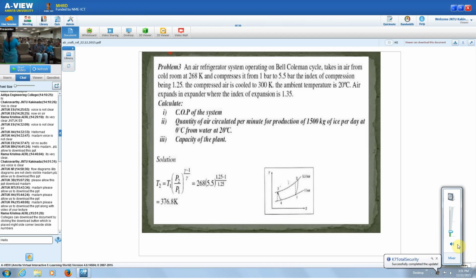With change in altitude, the turbine exit temperature is not much affected. With altitude height, the exit temperature should always be maintained at low temperature. Then only it can take more heat from the chamber to be air conditioned.